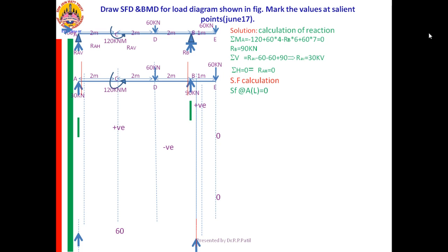The new load entering is 30 kilonewton and is carrying the left part up. That is why it is 30 kilonewton, but I am writing it systematically as 0 plus 30. 0 in the sense till the left it was 0, and when I am jumping to the right 30 is making its entry.